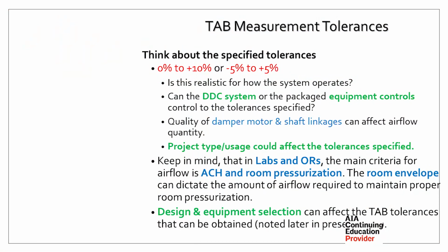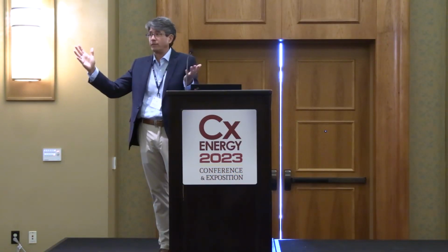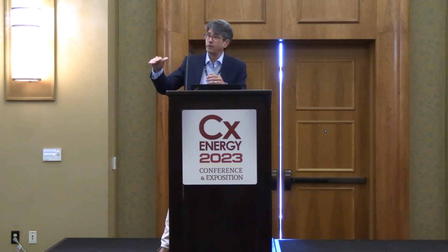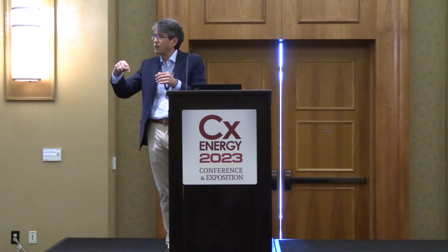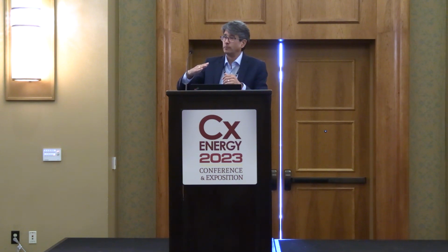Minimum flow. A lot of times what we'll do is back the unit down to minimum flow. So let's say we have VAVs connected up to the system. We'll drive all those, index those to a minimum airflow set point, see what the air handler does, make sure the air handler runs stable. Today, majority of your fans, I don't see falling off a fan curve. We've had it in the past. We get down to minimum, it falls off the curve and it starts rocking. So you'll run a test, drive your boxes to minimum, set the system up that way, or even on your pumping system, you might drive your system back down, back off so many control valves. So you want to usually go min-max cases.